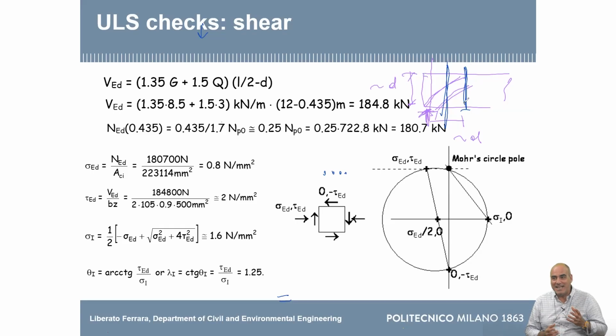Yes and no, in the sense that that angle, why is it happening? It's happening because the beam is deflecting, but close to the support the beam is rather a rigid part, so you just move that. So at this position here, you have not the full pre-stressing force, but you have a part of it because of the development length. And if this length is 0.45 or whatever, it means that we have about 25% of it.